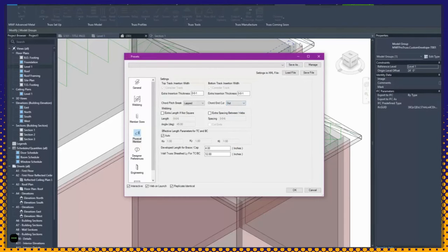So at the edge of the panel here, is it going to be in by using the center point, the interior edge and the exterior face of the roof? Or is it going to be out by placing the exterior or the shortest edge of the member to the outer face of the roof? That way it'll extend out and it can be chopped out. So that way it just adds a little bit of additional length, and your bill of materials will be correct that way as well. Okay? Well, it'll be correct either way. It's just depending on how you want the connection to show.